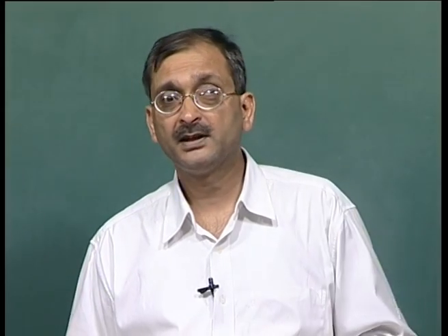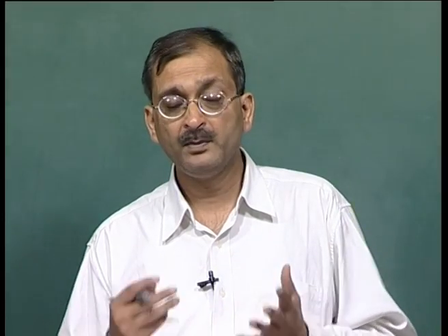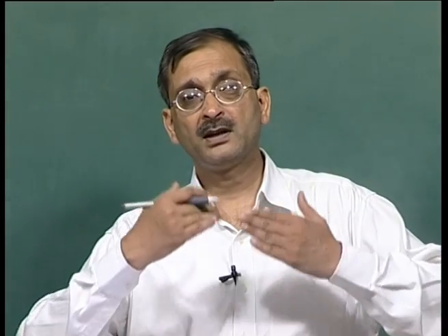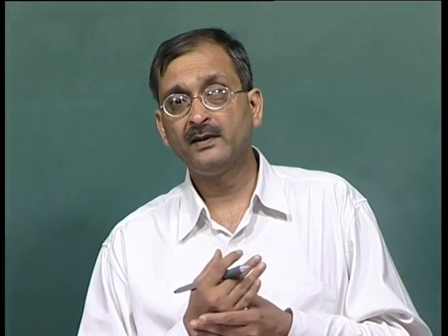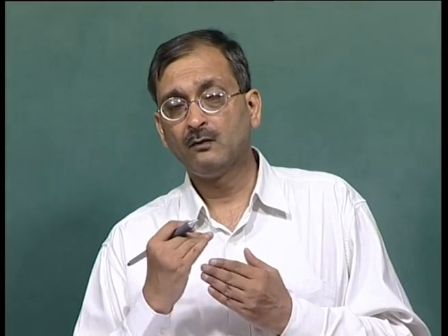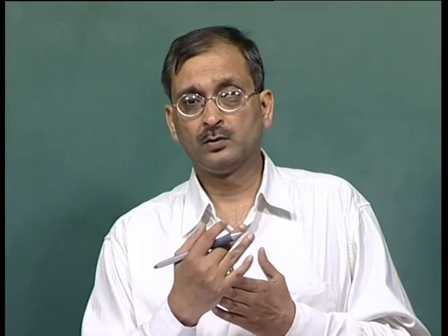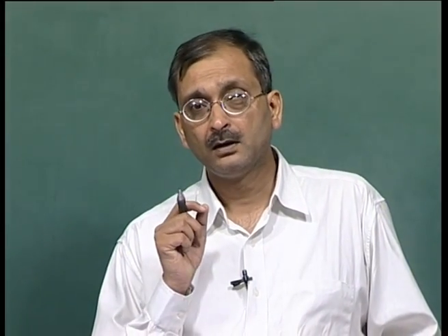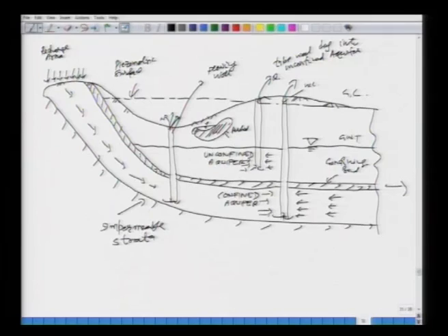What could be the possible ways of the recharge areas? We can dig wells into a confined aquifer and then we may have either a flowing well in which water will be coming out automatically because the piezometric surface is higher, and then also we may have a penetration well in which the water table is not above the ground. So, in that case we will have to pump the water out. Nonetheless, if the observation well or the pumping well is deep enough, then water will come from the confined aquifers. We can also pump water from the unconfined aquifers. So, these are the different ways of looking at it.